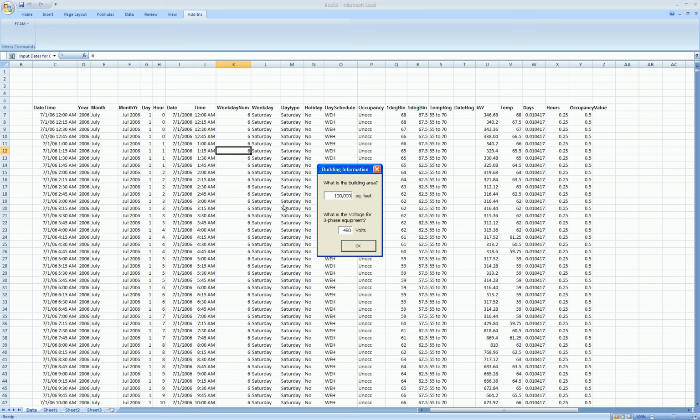For example, if you have a consistent set of data, it will automatically calculate tons from chilled water temperatures and flows. It will calculate a kW per ton. It will normalize any power measurement or power point by square footage if you input the square footage, various things like that. So it automates some other things that you may do as part of your normal energy analysis and makes it a little bit easier in that fashion. Another value of identifying your point names is that if you're going to use the PNNL building retuning process, having the standard point names is required to have those charts created automatically.